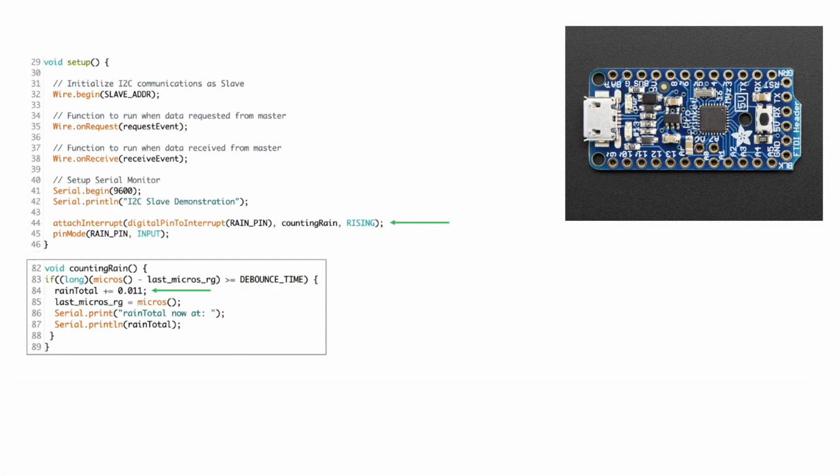The first improvement in software was to eliminate any conditionals in my interrupt function responsible for counting tips. Since I'm debouncing using a hardware remedy, there's no need for this filter in software, and eliminating the same addressed intermittent problems I was having with missed tips.